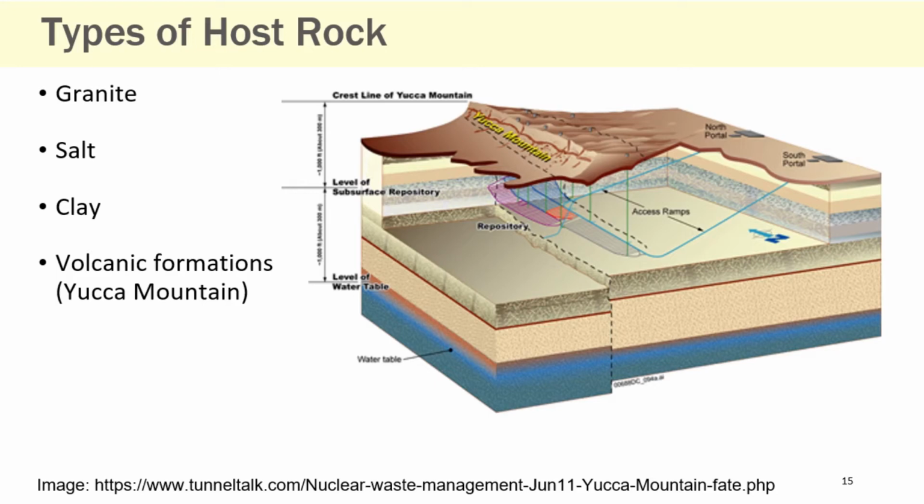It has a low water content and very good plasticity, so cracks are self-healing, but salt can contribute to corrosion, and the salt brines themselves have complex chemistry. Clay is a very fine-grained material with a high mineral content and can be used as both an engineered barrier and a host rock. Clay can have a very low permeability, causing slow water movement, and fractures in soft clay can be self-healing. It is chemically stable with strong sorption capacities, causing solute motion to be extremely slow.